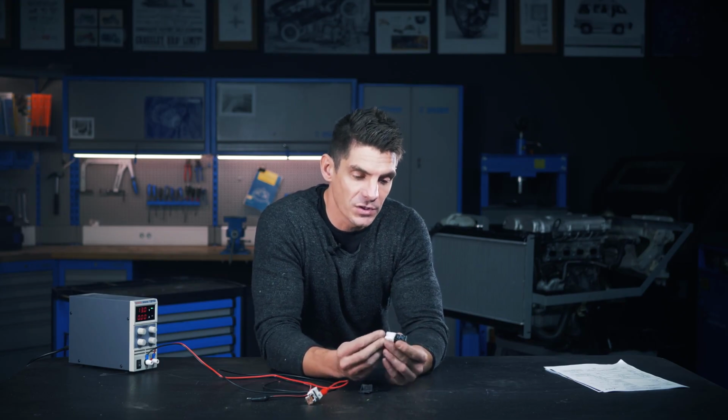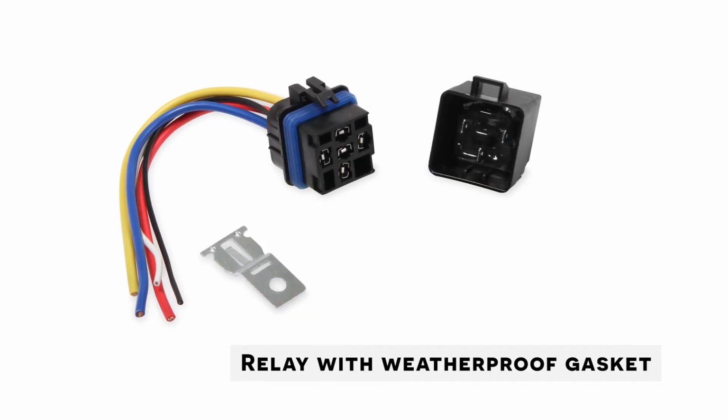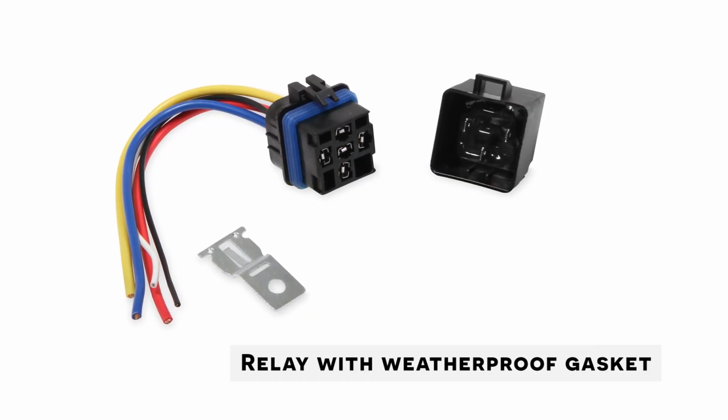So most relays that you'll come across are of a plug-in type like this one where it clips into a connector. You might come across a surface mount relay. It's unlikely on a vehicle, but possible. These ones are preferred because you can take them off and test them and replace them when they're faulty. Now, depending on where they live, you may also find a relay with a rubber hood or some sort of weatherproofing. There's also specialist relays like flasher units, injector relays, glow plugs, which have specialist functions.